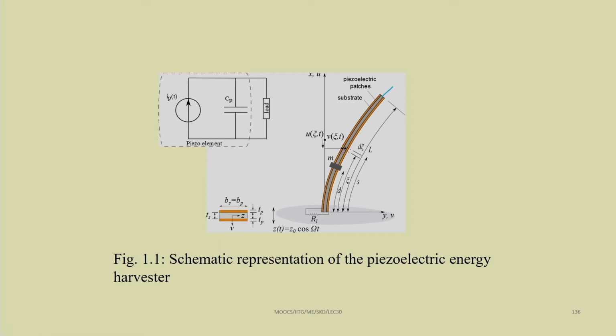Previously we have seen that by putting this mass at any arbitrary position, we will be able to generate internal resonance conditions. So, we can adjust this mass in such a way that the ratio of the frequency between any two modes can be controlled or can be taken in the form of an integer relation. In that case we can have the internal resonance conditions.